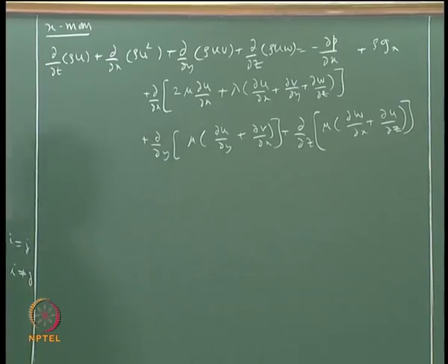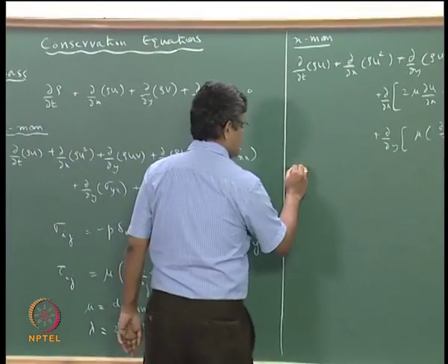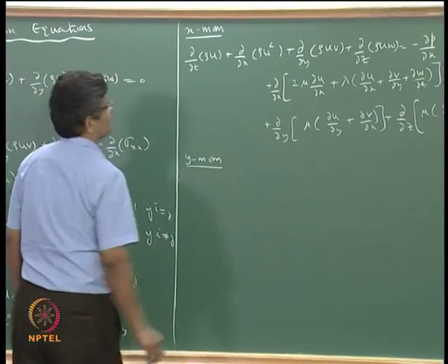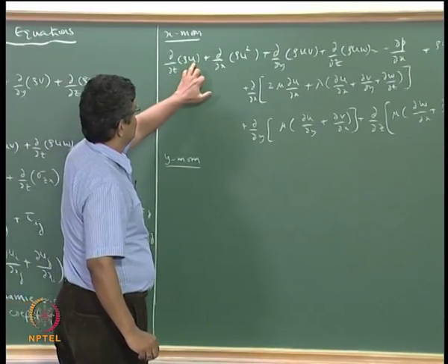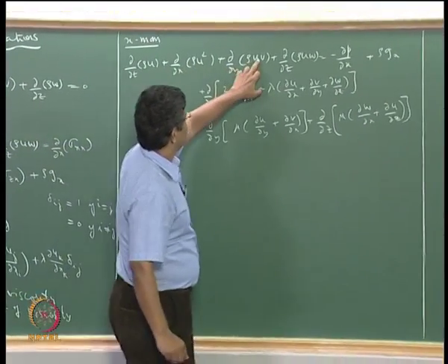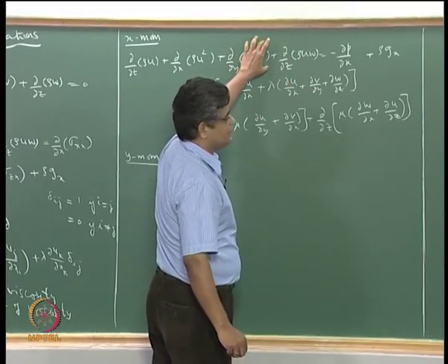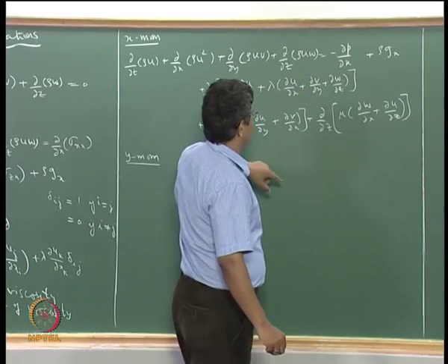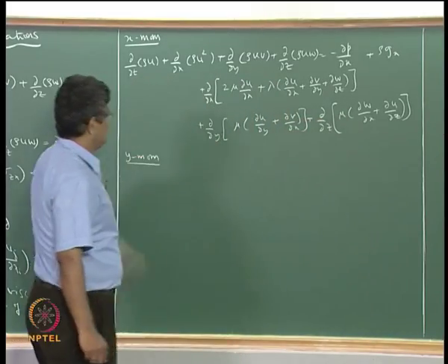So this is the x momentum equation that we have, and we can similarly write the y momentum equation in a similar way, taking the u, converting one of these u's into v's here. This dou p by dou x becomes dou p by dou y, and this becomes rho g y, the y component, and these things will also change.